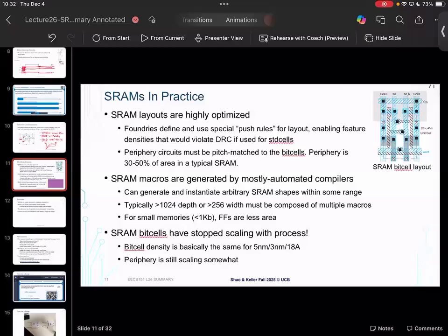Yeah, there are a few different reasons. One, you can think about, right? We said the bit lines are these huge capacitances. So the more entries you add, the more capacitance you have on the bit line. Eventually, you have so much capacitance that a single bit cell can no longer discharge it within a meaningful cycle time. So there are other constraints too, but that's an example of one, where eventually things just get too big, and the careful design decisions made around these SRAMs no longer would work.